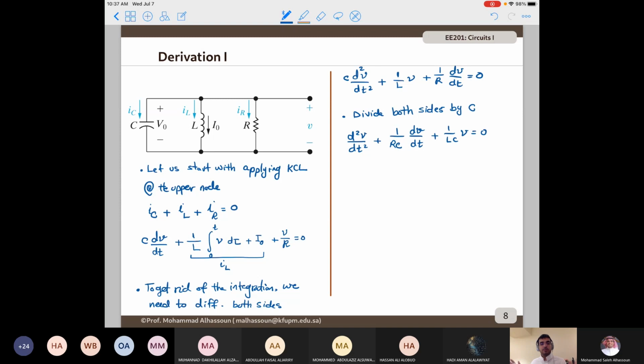Okay, we derived the differential equation that governs the circuit behavior. So now what should we do? We should actually find the solution of this differential equation. So just bear with me. What you have here is a function plus its first derivative plus its second derivative somehow scaled equals 0, which requires that the function and at least its first two derivatives are of the same form.